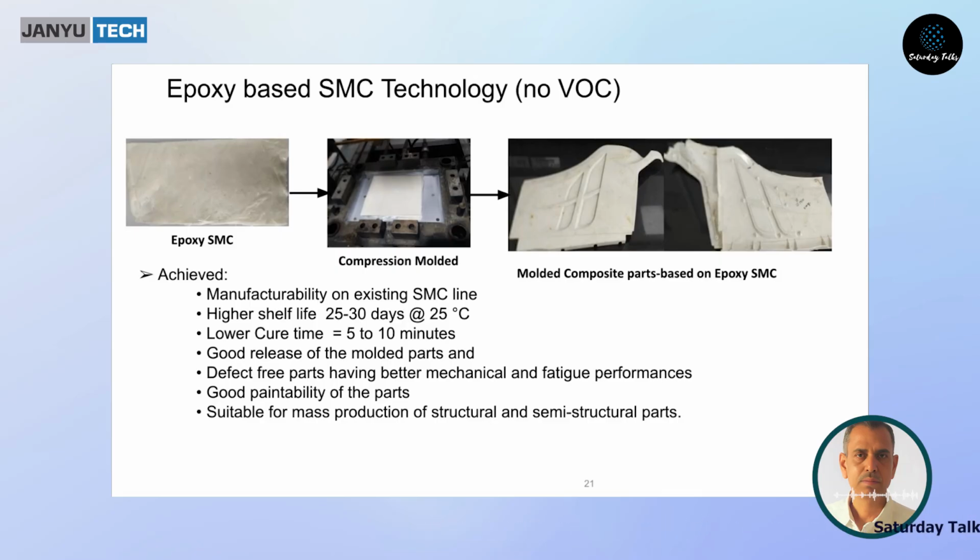The curing mechanism, the hardening mechanism for SMC technology is basically a free radical type of reaction, which starts and finishes very fast. But this reaction is not a free radical reaction. It takes place from the functional group side, a condensation type of reaction, without producing any byproduct though.